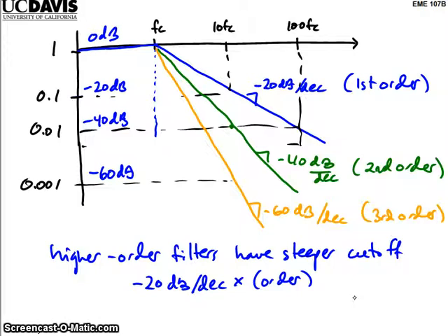Actually, in the DC motor lab, I had you use a filter to filter the tachometer data, and we used a third order filter for that. So that was a fairly steep filter. The program in MATLAB was a special filter design program to design what's called a Butterworth filter. You select the cutoff frequency you want and the order of the filter, and it'll design the filter parameters for you. I'll talk in just a bit about something more subtle in that filter, because it was for use on sampled data.